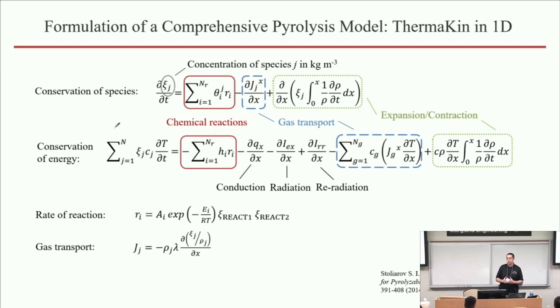Effectively, this expression gives you, depending on, let me circle back, depending on how you define the volume of your solid with respect to the concentration of individual species, this transport mechanism either approximated Darcy's law, which is pressure-driven viscous transport through the porous matrix, or it represents standard classical diffusion.